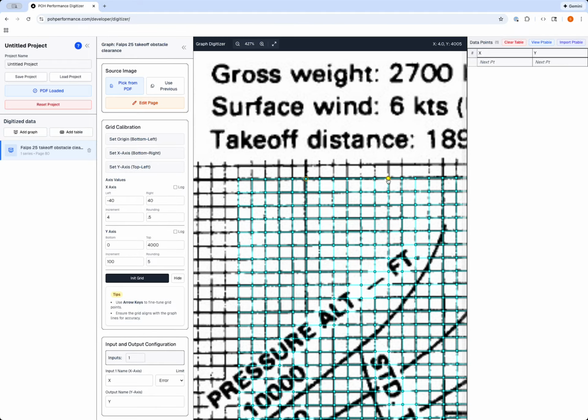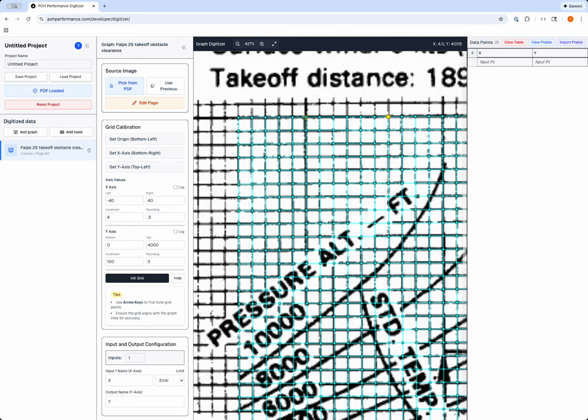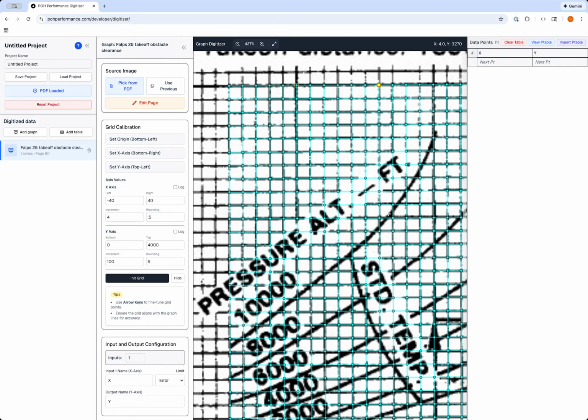And remember, with all the warping and the skew, the grid has to match the actual grid lines on the image, because when you sample, you're going to sample against the nearest points in the grid. So those points that are near those lines have to be very, very accurate. So I work from the outside in, trying to make things line up.